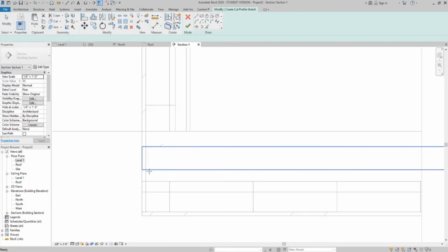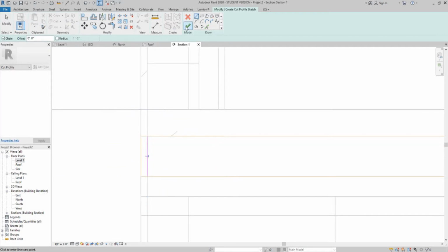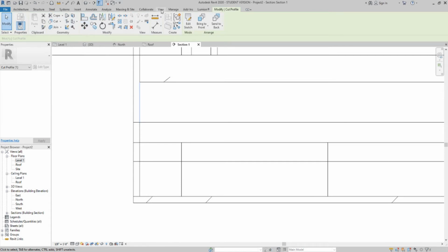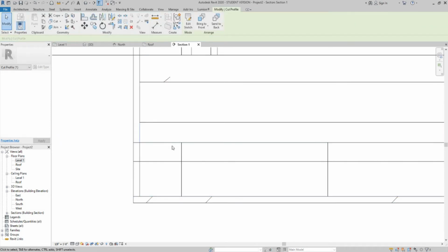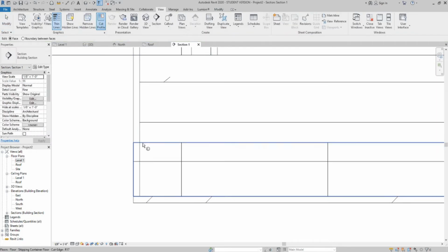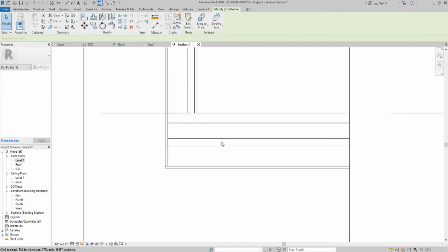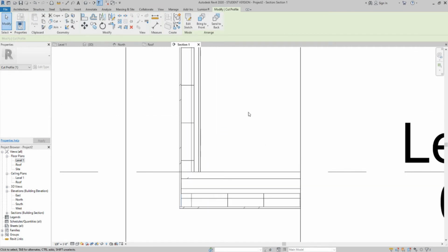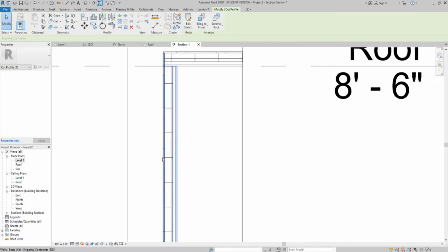Cut profile, click on that. Flip it, check it. View, cut profile. This next one. And cut profile. I bet if I drew it going up, my arrows would go the other way. Alright, so now that I have this, this detail looks pretty good. And so the only other thing that we could change is the profile of the metal, the corrugation.